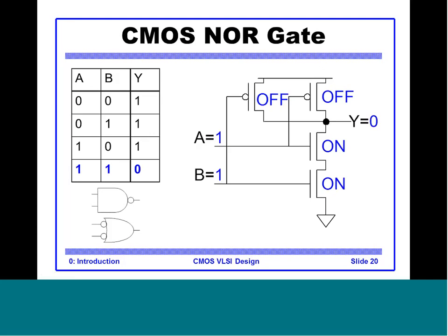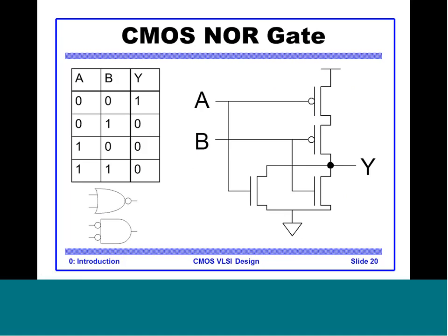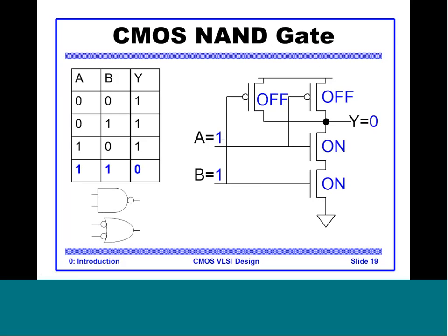So if we notice here, the basic gates in CMOS technology are inverter, NAND and NOR. Whenever, let's say, you want to make an AND gate, what you have to do is connect an inverter. There will be an inverter stage after the NAND stage. That means a 2-input AND gate will use up more transistors than a 2-input NAND gate. That is 2 transistors extra for one inverter.